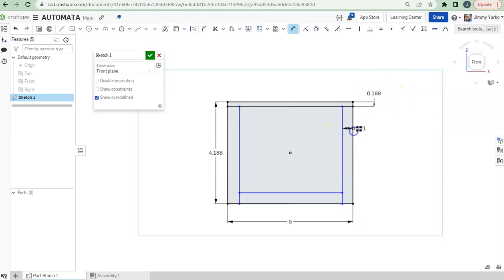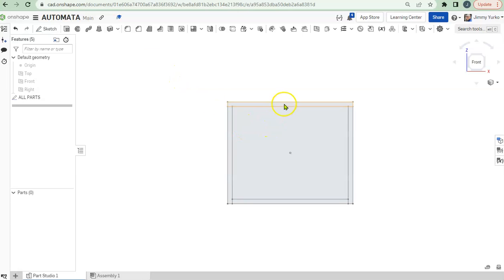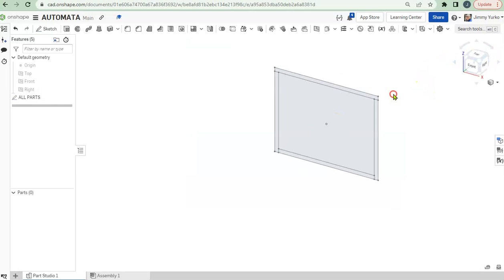and 3/16 thick. This will be a great use for variables, and in this program you do have the ability to do that. We'll set that up in another video sometime, because then we could, since all of these dimensions are the same, we could clearly and easily use that variable. But let's call that all parts and finish that sketch. So here we have the top, the left side, the right side, the back, and the bottom. Let's go ahead and turn that into a 3D object.